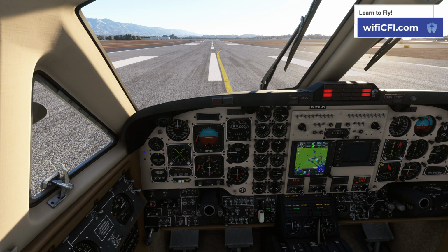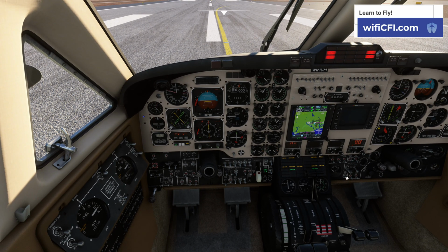Stall gear warning test, come down here. So we have a stall warning test in this plane. I don't think it works. It didn't work last time either. But you would push that up and you'd hear the stall warning horn. Pushing it down, if it was installed, you could also hear a gear warning horn. So that is installed sometimes, not installed other times.